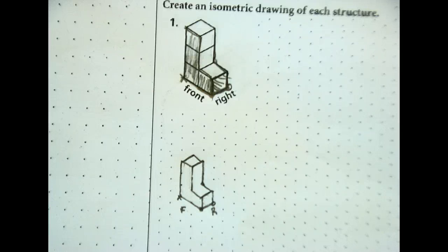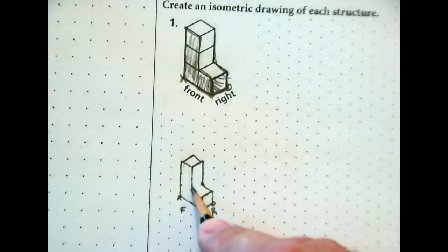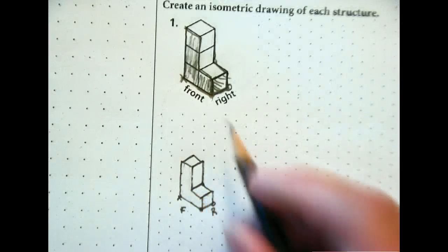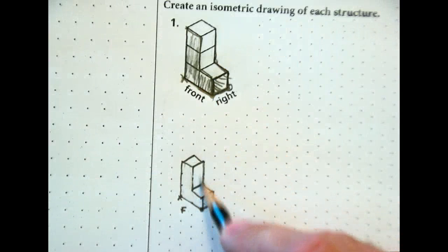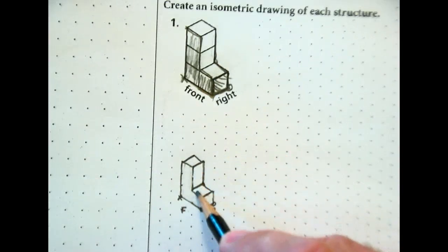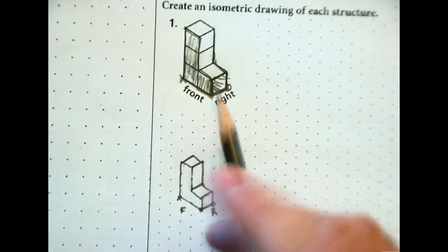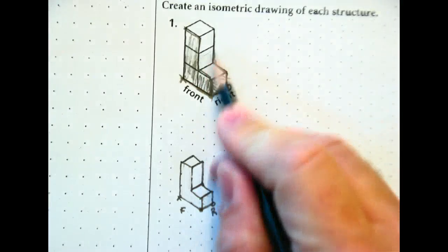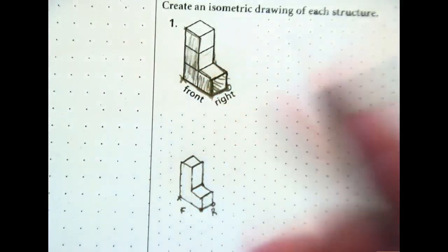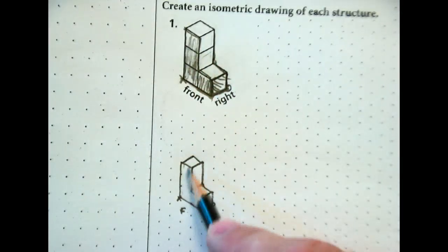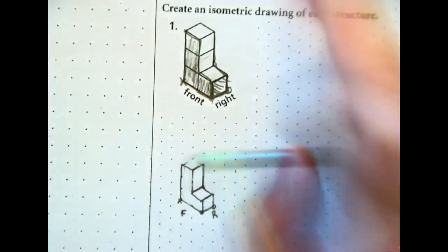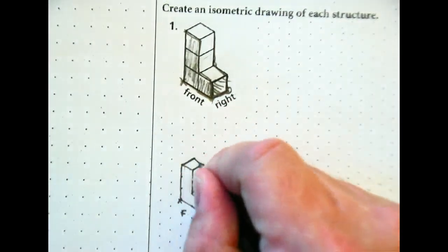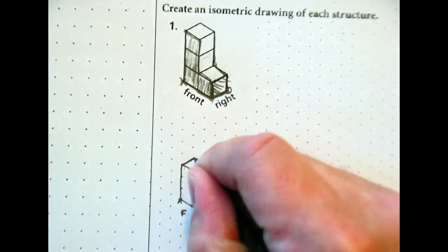Chase? It's right at where the 2 bottom blocks start, right there. Yeah, because it's a turn, it's a change in depth. If I was looking down on this shape, that's a change in depth. This is tall, and all of a sudden I hit a platform, so at every platform. Notice in their original shape, they had all these marks where the blocks would be, just like you would if you looked at your figure. In our isometric drawing, we do not put all those lines. The only time we put a line is if it's a change in depth. Okay?